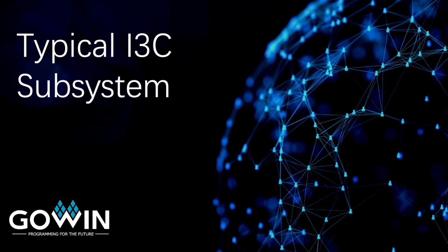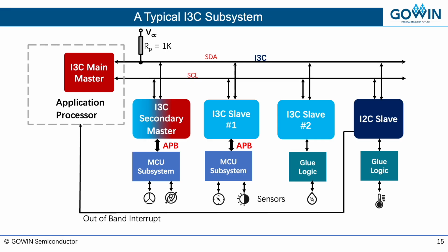What does a typical I3C subsystem look like, and how different is it from an I2C subsystem? Let's examine. Let's go back to the sensor hub that we discussed in an earlier slide. The data is gathered from all the sensors in the system, processed by the application processor, and then sent to the main CPU upstream. One thing to note is that I3C is a multi-master environment, but at any given time there can be only one master on the I3C bus.